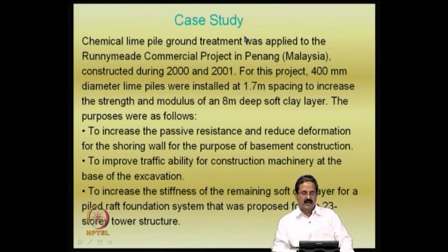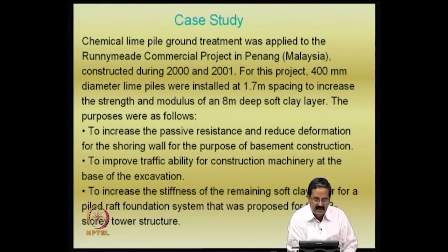Now, I would like to describe a few case studies. One is actually a case study in Malaysia. It was constructed in about 2000, and in this case 400 mm diameter lime piles were installed at 1.7 meter center to center spacing to increase the strength and modulus. Okay. Like an example that I just discussed, one can use that method to check this.